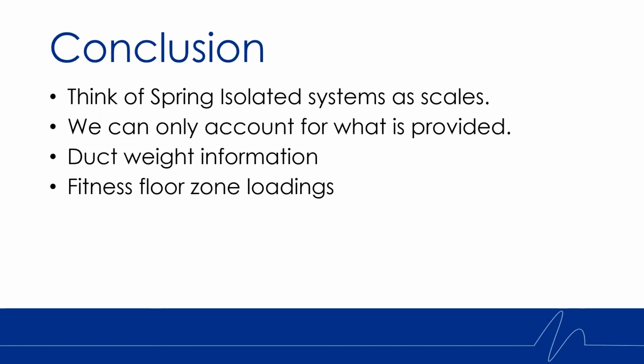So the big takeaways that I would like for our viewers is to think of the spring isolation system as a scale. If the springs expect to see a certain amount of weight, they will deflect as selected. Hence, if we go back to the 37-pound example, that spring will deflect as anticipated. But if you add an unexpected weight of a chandelier or a ductwork, now you've tipped the scales and you're either over deflecting or under deflecting.